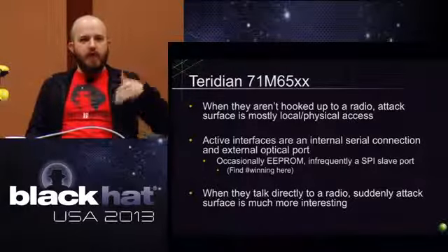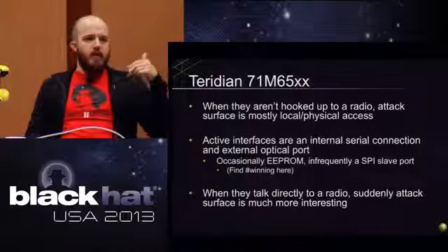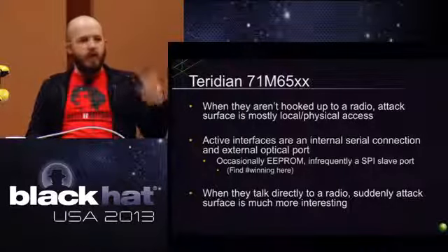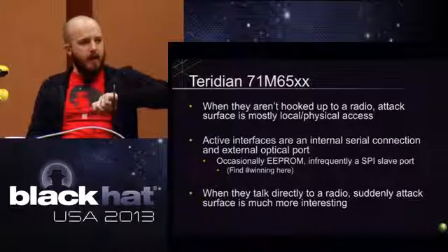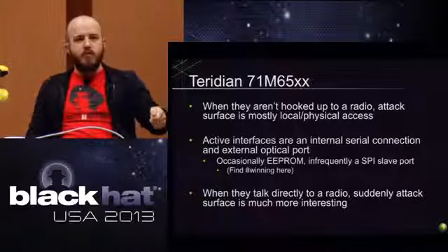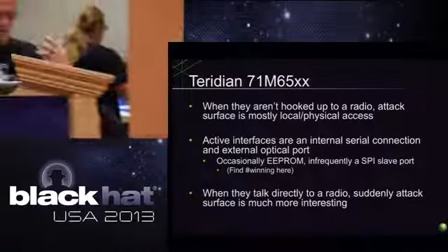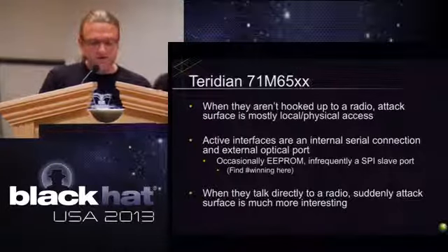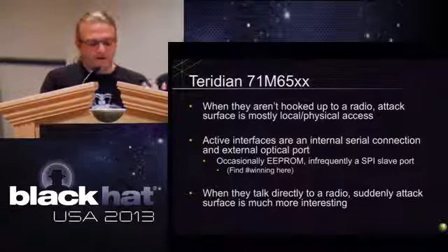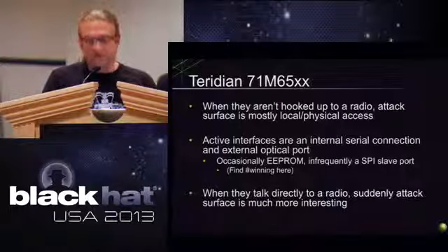Or it could just be doing straight pass through, and the Teridian chip itself could be speaking something like ANSI C12.22, which is the one for network communications, and then you've got actual packets terminating inside the Teridian chip itself. So yeah. When they're not hooked up, you have to have physical access to be able to pop this. As soon as they're hooked up to any sort of radio interface, now you actually have a valid remote attack vector, which is logical, and it's not really jumping anywhere from where we're comfortable with.